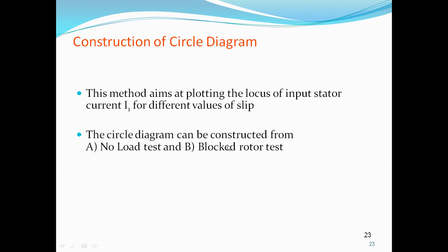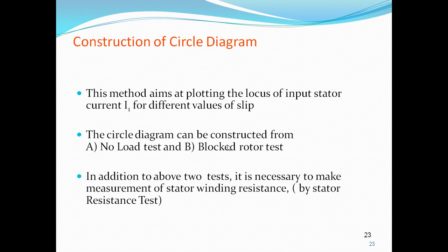The circle diagram can be constructed from no load test and blocked rotor test. In addition to the above two tests, it is necessary to make measurement of stator winding resistance by stator resistance test. R1 also we required, that is we got from stator resistance test.